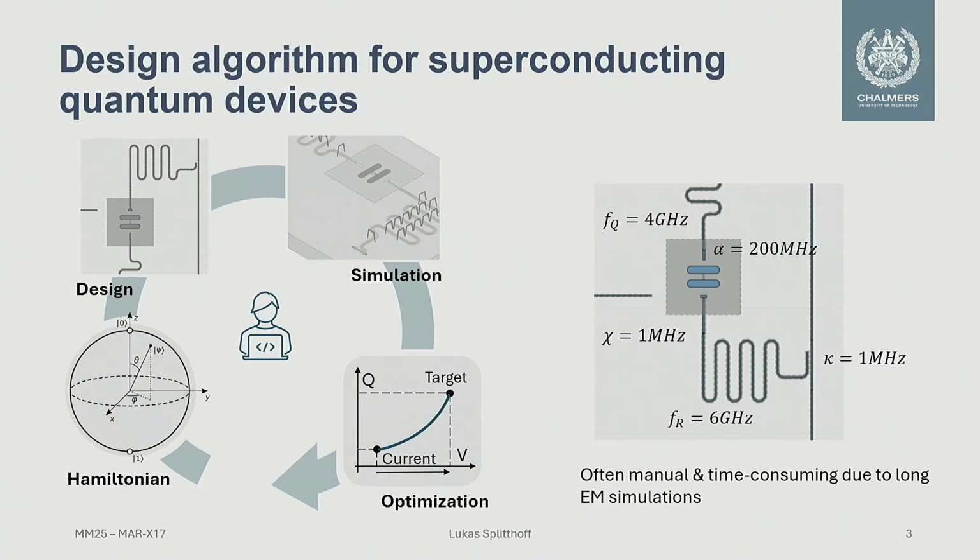And now many other packages that we've also discussed here in the session today address this point in very different ways. But most often we would make small changes here to the capacitance island, also to make a single qubit example like the one here presented with 5 parameters work. But it's manual and time consuming in most cases. And what I'd like to show you today is our approach and our solution towards this optimization problem, which is slightly different to the SQuADDS approach that we've seen before.